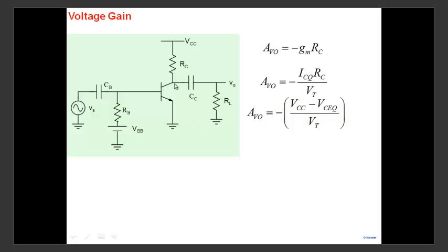Well, if I make it very low, it will go into the saturation region, and we said 0.2 is our limit. So maybe you can make it 0.2 or 0.3, let's say, to stay away. If you make it 0.3, then the maximum possible gain that I can get from the circuit is VCC by VT, because if VCC is large, 5 volt, 0.2 or 0.3 doesn't really matter. So the maximum possible voltage gain depends on VCC by VT.